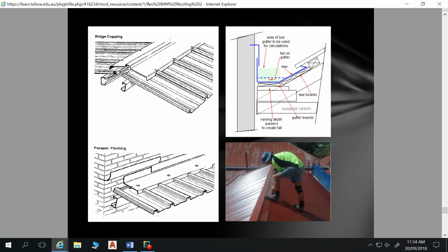So if you've got a form that goes over the top, to the extent that form carries down, I'd carry your flashing inside. Certainly, that flashing has to have a slope toward the outside, so the water has to go toward the outside, and then it's carried in here.